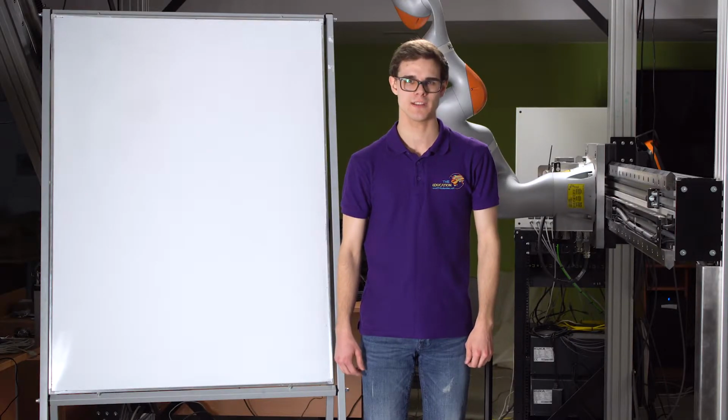They have relatively low voltage, around 1.2 volts, and relatively low capacity. These batteries also have a so-called memory effect. Depending on charge and discharge cycles, they lose capacity over time. The next type are lead-acid and gel batteries. They have a voltage of 12 volts and large capacity, up to around 20 ampere hours. They are used mostly in cars to start the engine or in UPS systems to maintain voltage when the primary power supply is out of order.